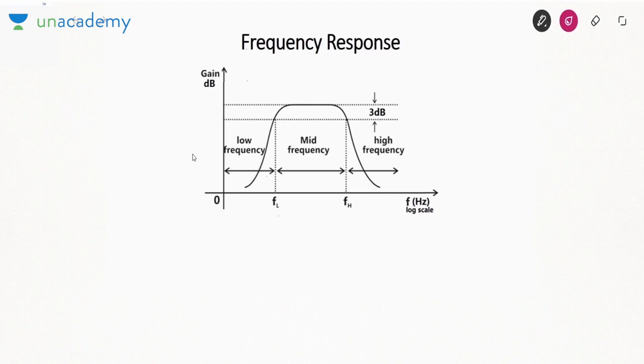But practically, when we talk about electronic circuits, capacitances play a very important role. Similarly, when we talk about electrical circuits or high power circuits, their inductances dominate. So you can't ignore these frequency dependent devices such as capacitance and inductance. These are also termed as parasitic, because they are present inside the device, though they may not be desirable. Capacitances are mostly considered in low power circuits or electronic circuits, and inductances are always considered in high power circuits or electrical circuits.